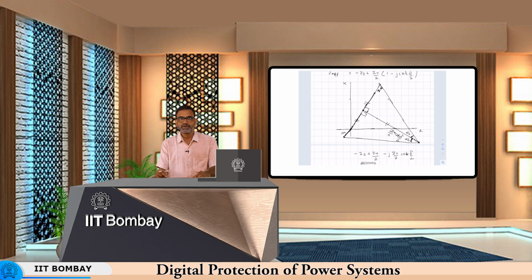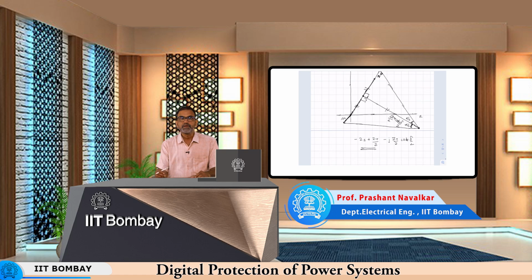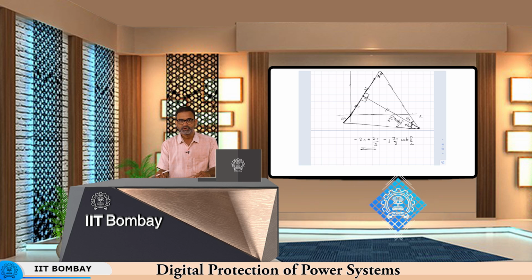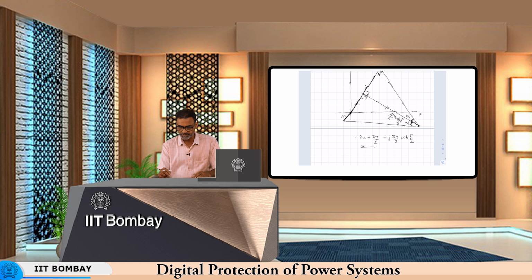So, we discussed power swings in the last lecture. We had stopped here where we drew the power swing on the Rx plane and looked at what the relay would see on the Rx plane. So, this is what the impedance seen by the relay is.